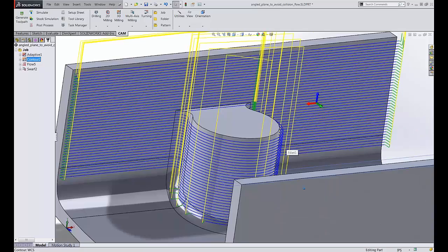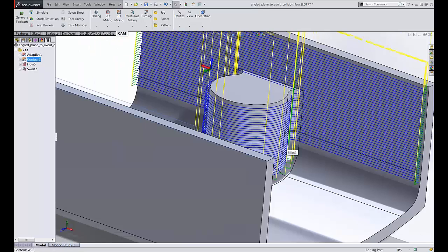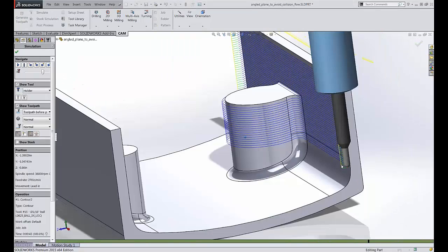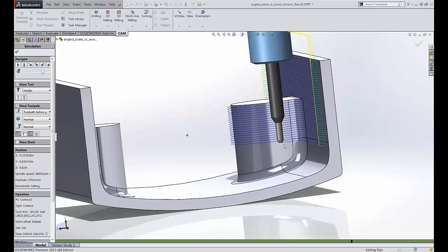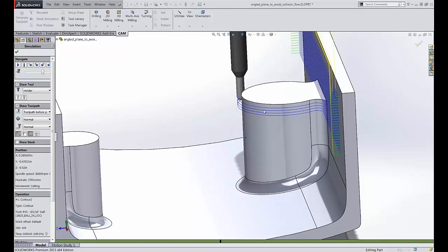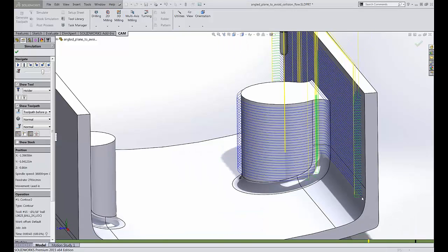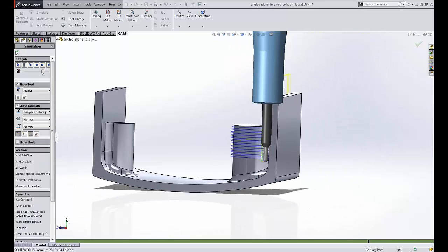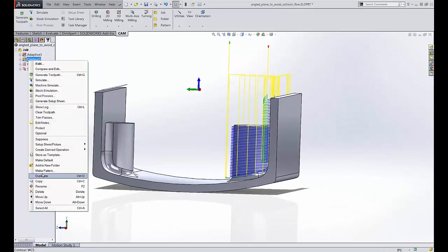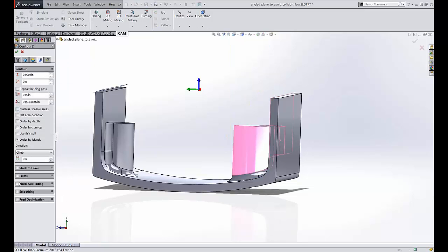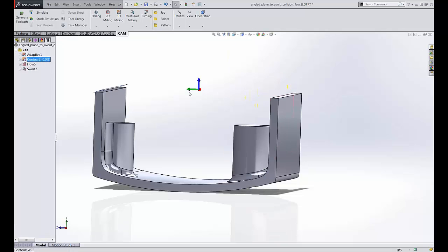Okay, so this is a fairly clean toolpath that we've got going on here. It's just a 3-axis 3D contour, but obviously it has some problems. There's going to be tons of places where the shank is rubbing or just plain colliding. And also I think if we jump way later in here, eventually we get some tool holder as well. So that's bad. We don't want that. Let's take a look at what happens if we just enable it and we'll give it, already got it in there, 30 degrees maximum tilt.